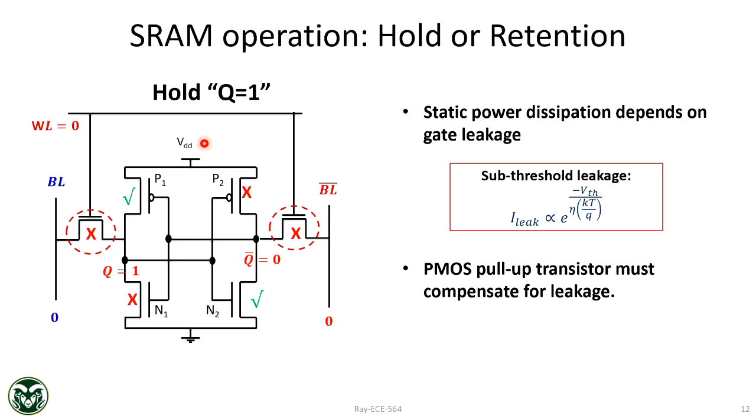But there are a few cells, maybe 0.001%, 1 out of 1 million, that can retain data at maybe 0.3, 0.4 volt only. So your data retention voltage will be defined by them. That's the statistics. In the memory industry, when I was working, statistics was everything. You don't worry about the median. Median will always be good. We always worry about the extreme cells. So this is one example. Your data retention voltage will be determined by these extreme cells, which have high leakage. Because of high leakage, they have high data retention voltage. So that will decide what is your minimum hold voltage that you can have.